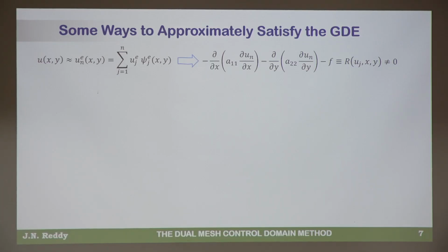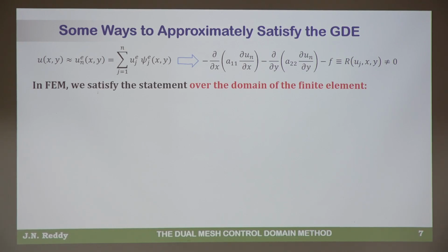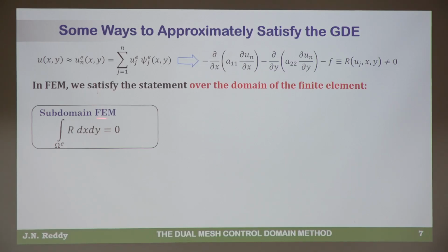So our goal is to somehow minimize the residual. How you minimize can be any number of ways, and that is where different methods differ from each other. So in finite elements, you could think of taking the residual and making it zero on a typical element. So I want you to think at this moment, what does R have inside? It has these unknown nodal values. And just to fix your thinking, think of a triangle with 3 nodes. That means there are 3 unknowns, 3 nodal values. And this equation will give only one equation in 3 nodal values. So it's useless. We need 3, right?